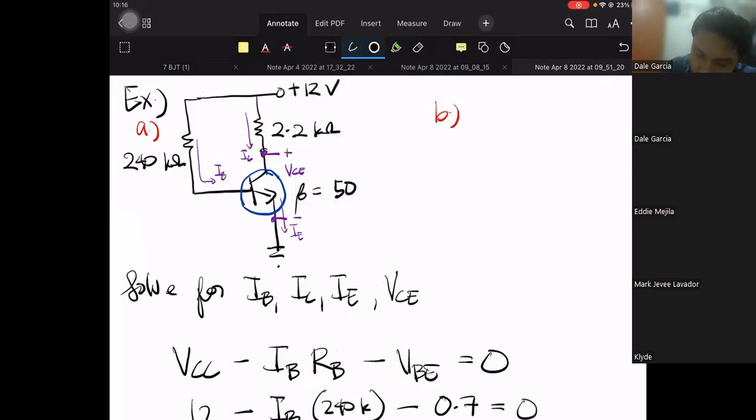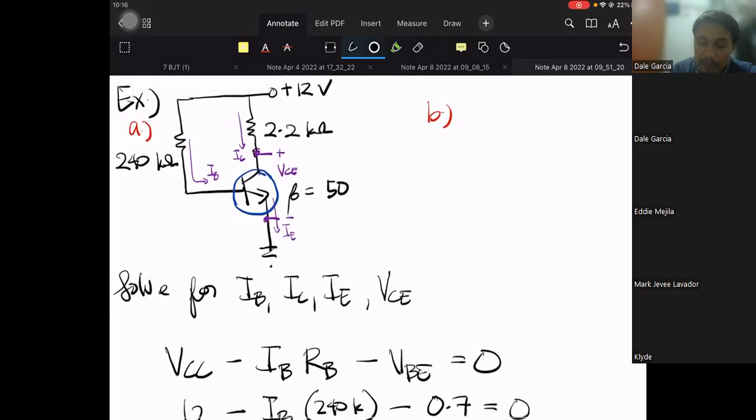I'll give you another situation. What if the transistor is destroyed, or needs to be replaced? Burned, for whatever reason. We need to pull it out, desolder it, then replace it. But because it's destroyed, we can't read its part number. We do not know what kind of transistor this is. So we replace it with something else. Let's say we know its original beta is 50, and the replacement transistor has a beta of 100.